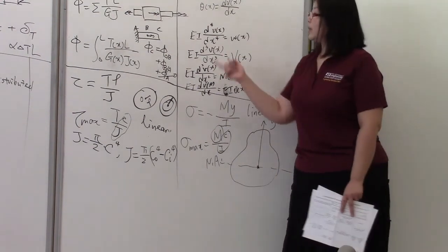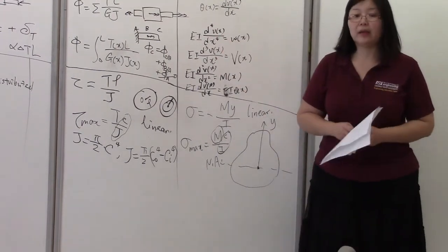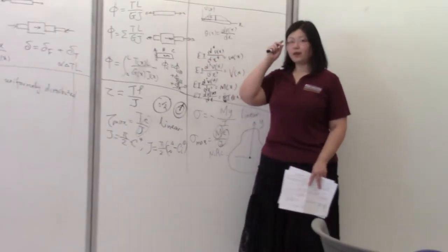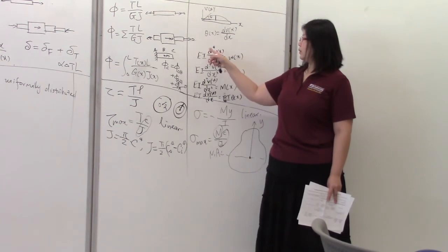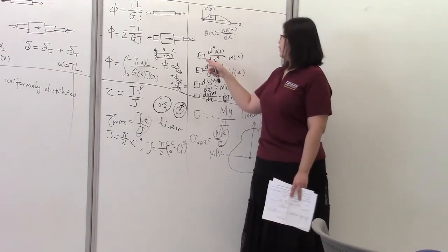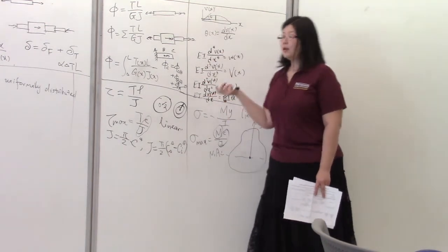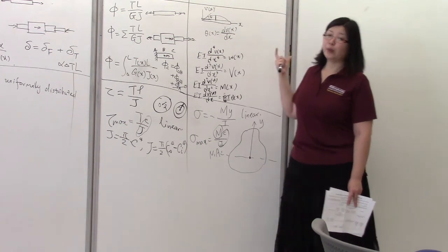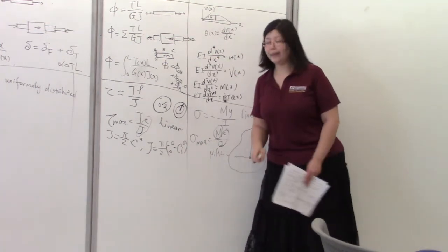Now this is assuming that EI is constant everywhere along the beam. If that is not the case, if these are continuous functions of x, then you need to include them inside of the derivatives. Or if I changes or E changes, then you have to do this for different segments of the beam such that within each segment you have constant EI.